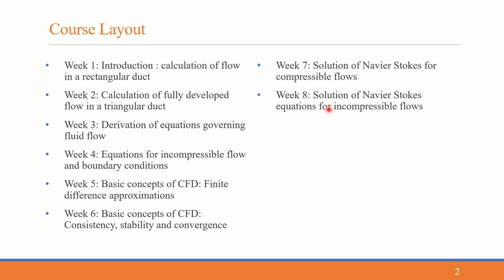And week 8 is about solution of Navier-Stokes equations for incompressible flows. When we are talking about incompressible flows, the situation arises where density is no longer varying, it is constant. So we need to take it out as a constant in the continuity equation. In the continuity equation the density term is absent, whereas in the momentum conservation equation the density term is present. So we are not able to decouple it, not able to solve it similar to how we did for compressible flows. So there are various other techniques.